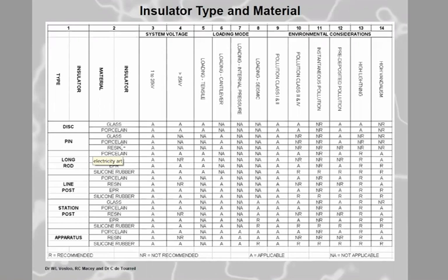It's got in it an ester, which has a double bonded oxygen. It's prone to hydrolysis. So all your cycloaliphatic will chalk because of those little double bonded oxygens. It will chalk, it will go white. Put your hand over it, it's like PVA paint.